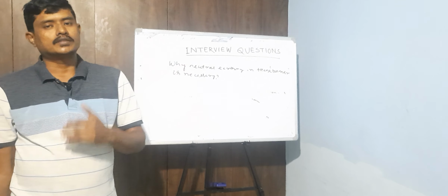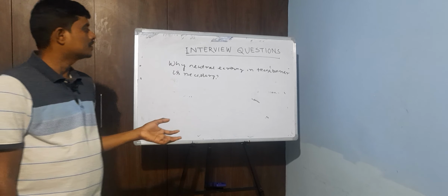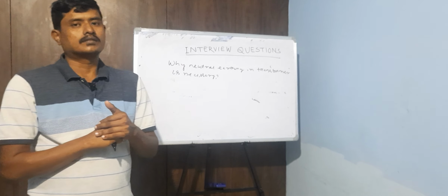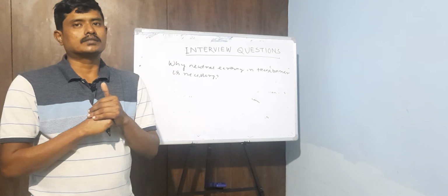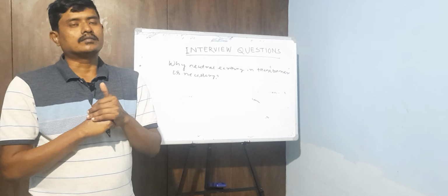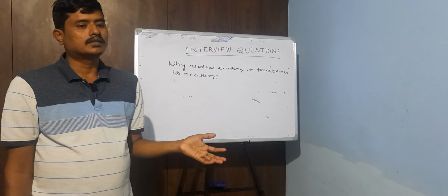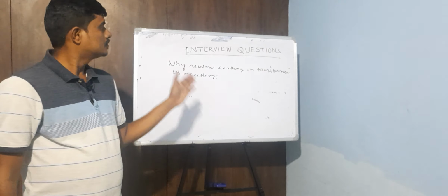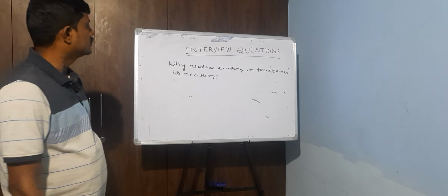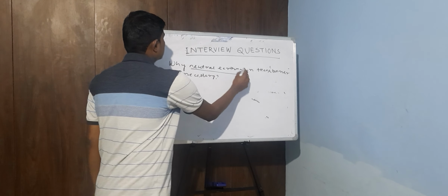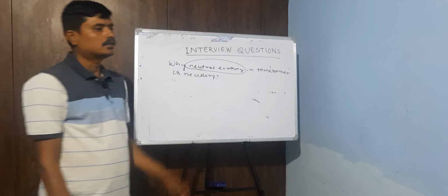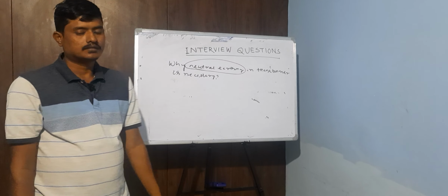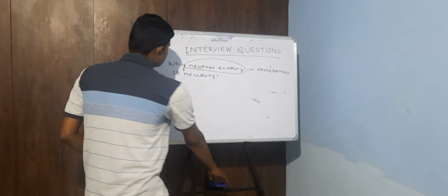If we remove the neutral earthing, the secondary voltage will be unbalanced. There is no stable voltage in the secondary. If any unbalanced current flows in one phase, that will distribute in the other two phases. That's why we provide neutral earthing, grounding to the neutral. It protects the equipment and maintains stable voltage in the secondary. Okay.